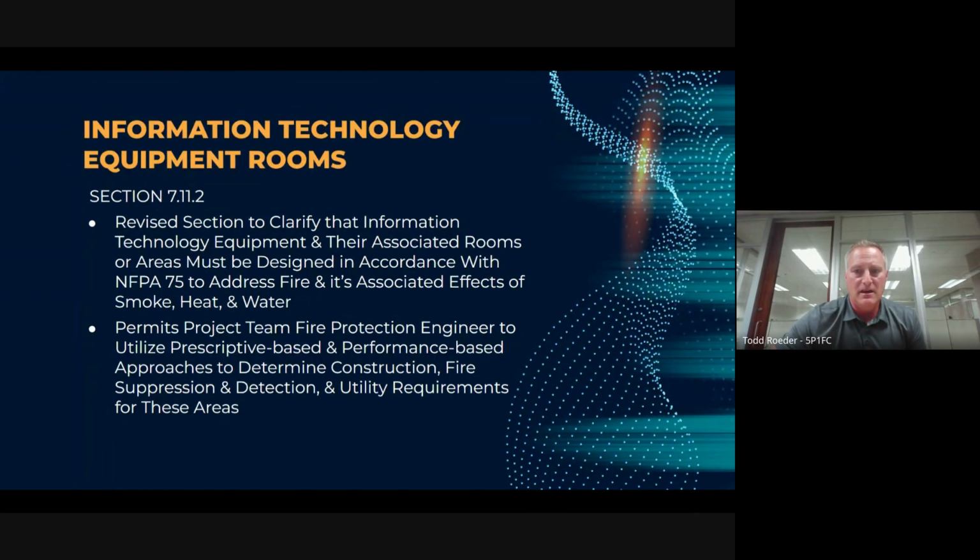I think the bigger of the two revisions is the fact that we now allow the project team FPE that we've talked about on a couple of the previous slides to utilize either a prescriptive-based and/or performance-based approach to determine construction, fire suppression, detection, etc. for these spaces.